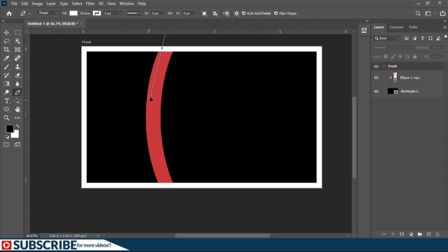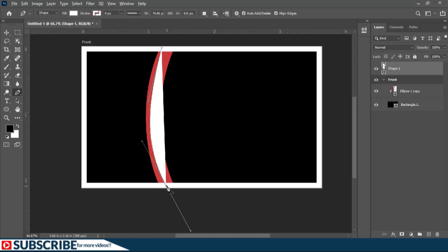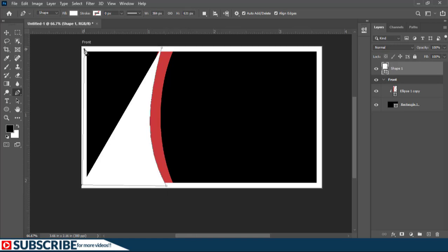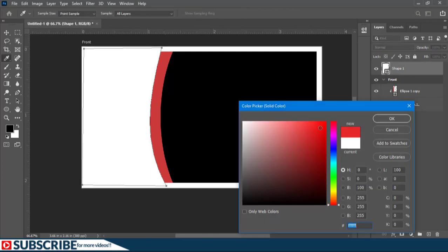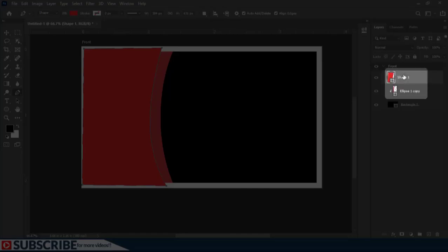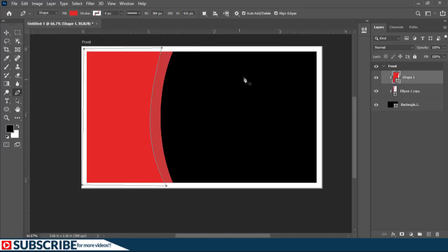My purpose now is to make sure I create a shape path that follows this path I've created, or this reference guide. So I'll just click there, come somewhere around here and click again, and just try to align it like so. Now I'll hold the Alt key, click here, just click here, and hold the Alt key and just click here. Let's double click inside here and pick just any random color for now. I'll hold the Alt key and clip it. As you can see, it stays just within the original dimensions.